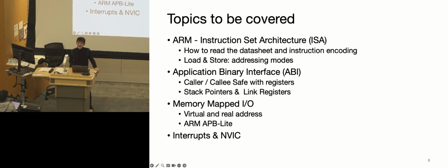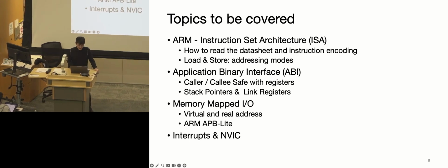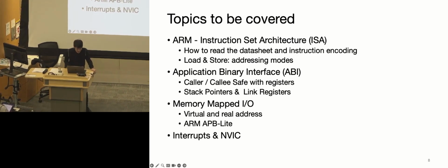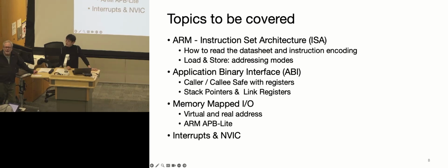What's the difference between APB versus the APB light? For the APB light, I believe that's one of the assumptions when we do the GPIOs, we have the GPIOs to be as a APB instead of actually an AHB, like the high performance ones. What was the question again? Basically the difference between the APB and the APB light that's on the slide.